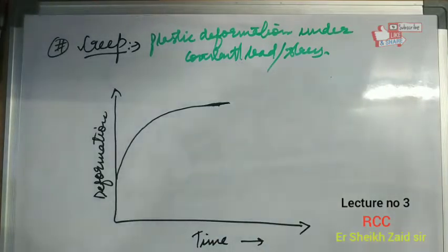Initially plastic deformation grows rapidly and reaches highest intensity in the first 3 to 4 months after the application of load, and then continues to increase gradually, approaching the limiting value in the period of 5 years.